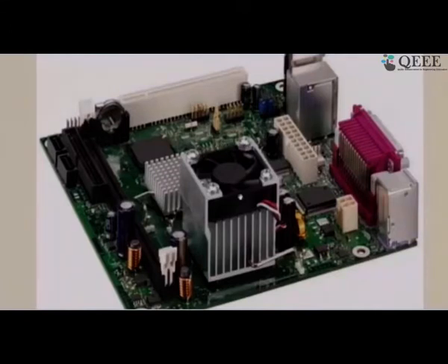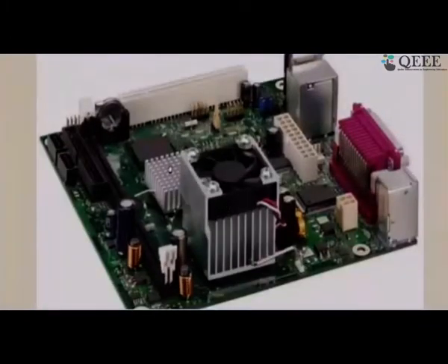is a fan. So what you have done here is that heat generated when the microprocessor does operations, that heat is quite substantial, and as we put more and more transistors on that chip and we drive it faster and faster, the heat generated, which is basically nothing but I squared R heat dissipation, that increases, and so there is conduction taking place through this, and then we have taken the ambient air inside this box, blown over it, and that air takes away that heat. So this is an example of forced convection for cooling the chip.